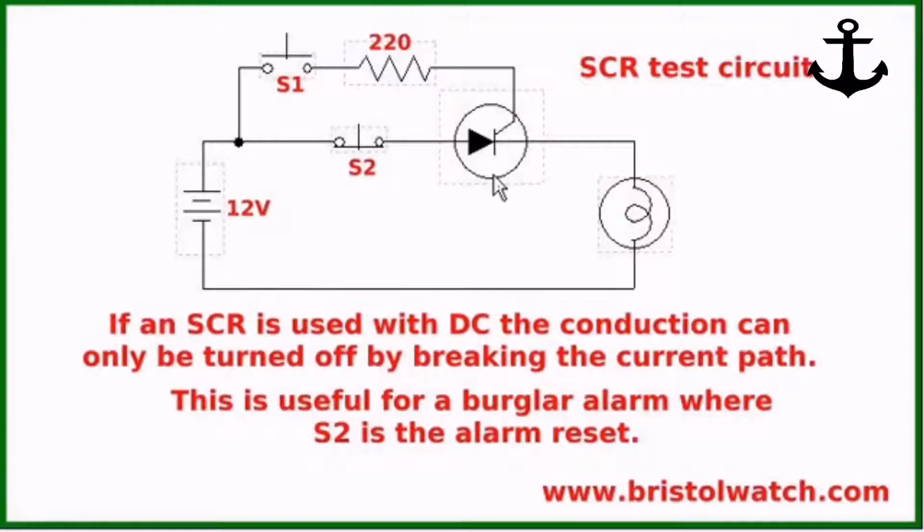So remember, if you have a DC source and you are using it with an SCR, it will not turn off until you break the current path.